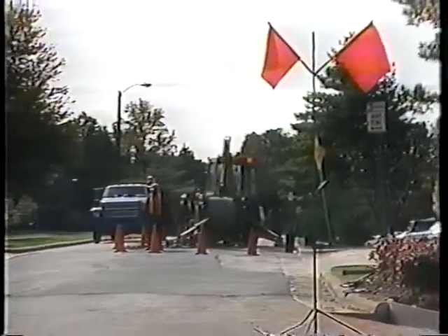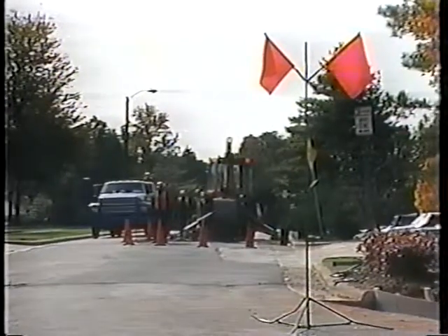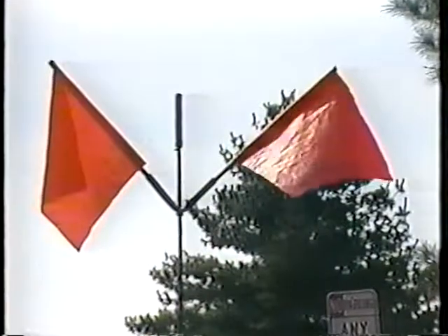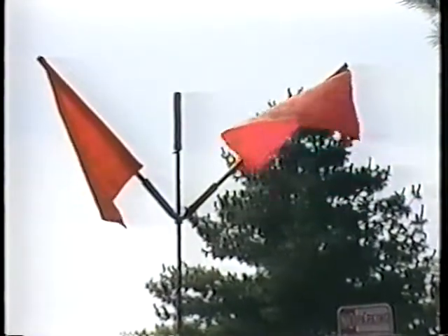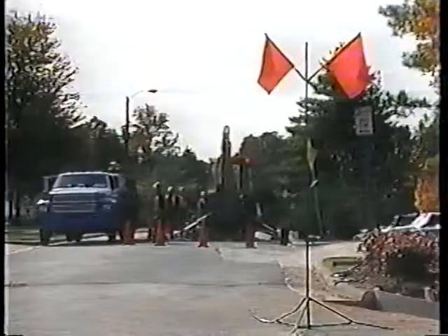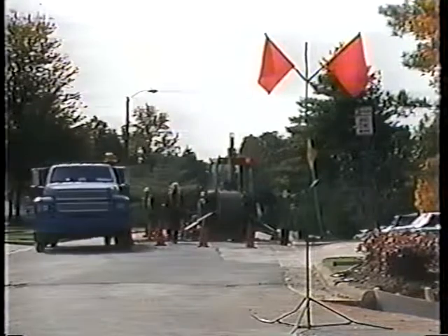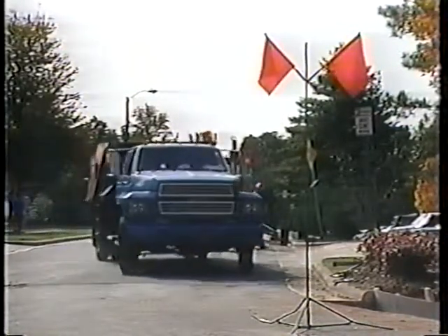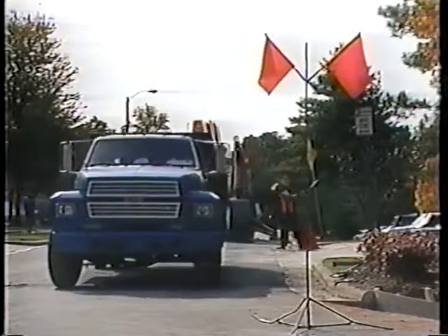High-level warning devices are tall portable stands with flags that are visible above the traffic and parked cars. They have a minimum of 2 orange flags, 16 inches square or larger, at least 8 feet above the roadway. The devices may be used with a sign or flashing light attached, or they may be attached to vehicles used in mobile work operations.